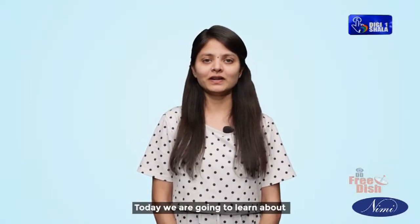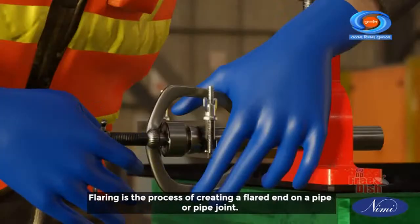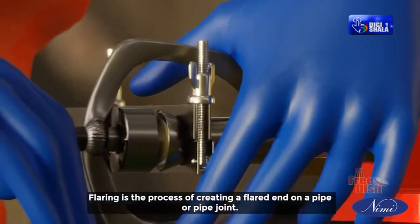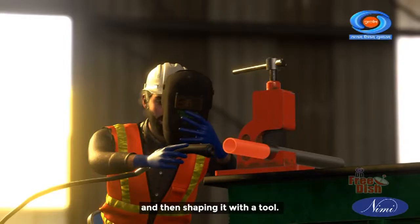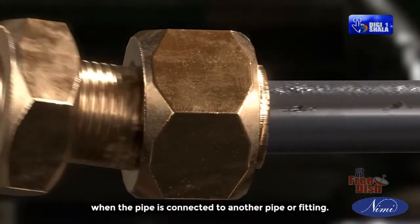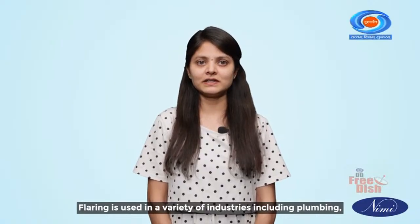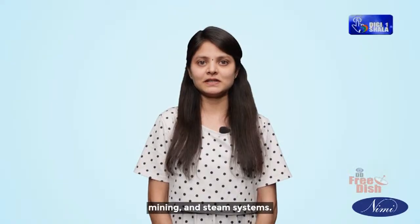Today we are going to learn about flaring of pipes and pipe joints. Flaring is the process of creating a flared end on a pipe or pipe joint. This is usually done by heating the end of the pipe and then shaping it with a tool. The flared end helps to create a seal when the pipe is connected to another pipe or fitting. Flaring is used in a variety of industries including plumbing, oil and gas, mining and steam systems.